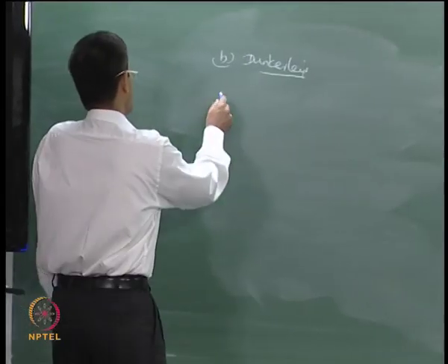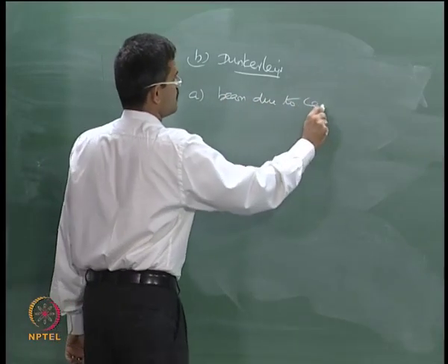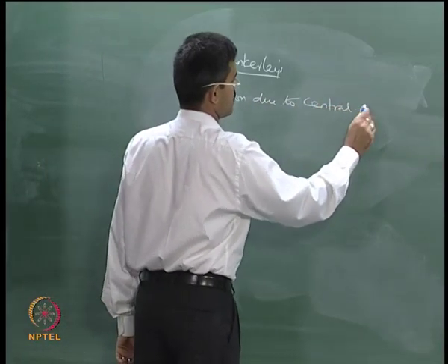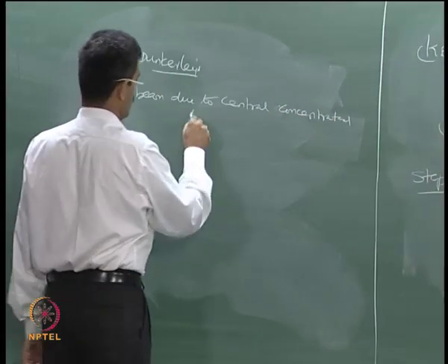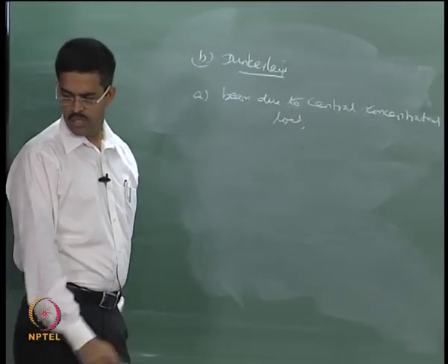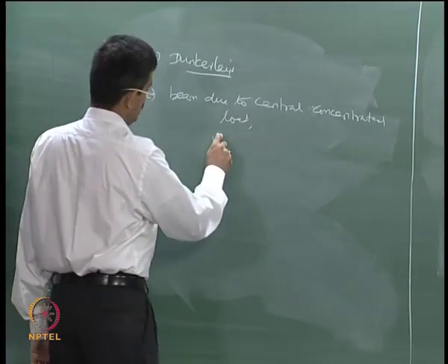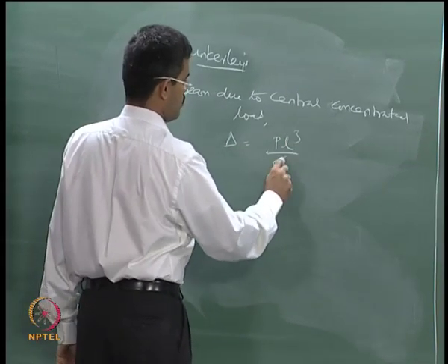So, if I am talking about any beam due to central concentrated load, we already know the deflection is simply, let us say, PL cube by 48 EI.